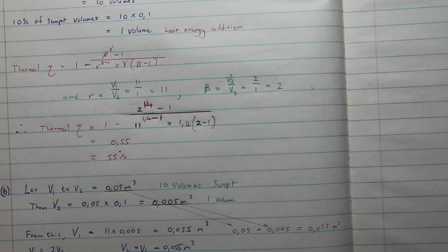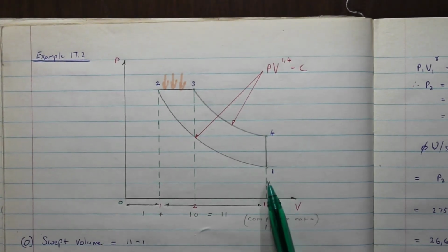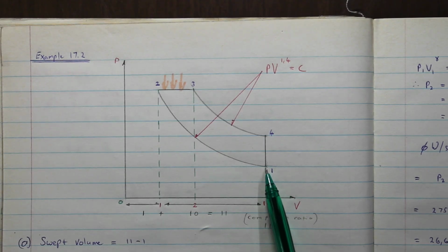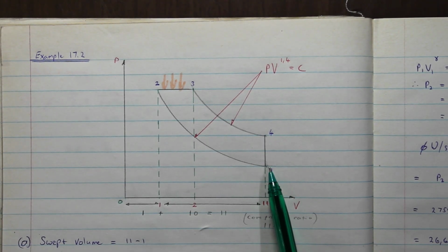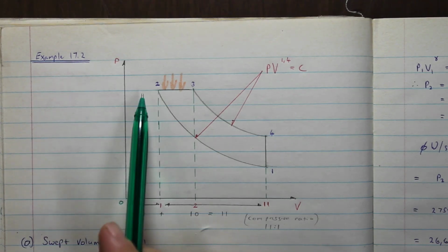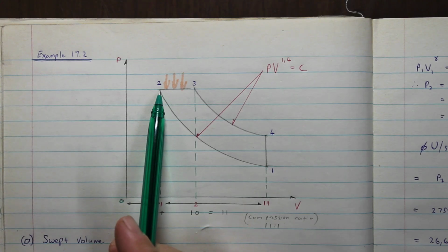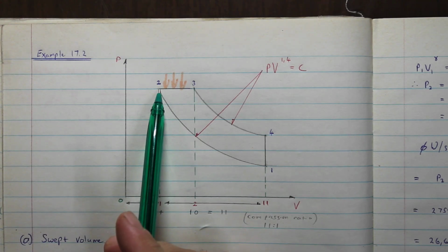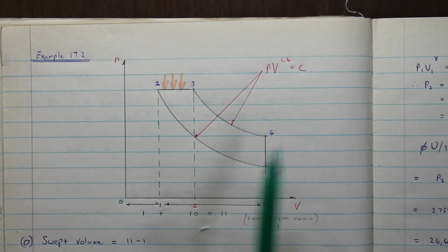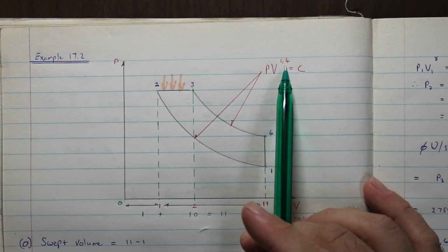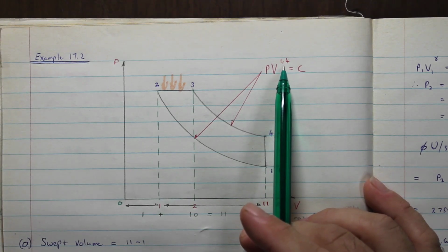Now the pressures. We have the inlet pressure, they told us, at 96 kPa, and they even told us the temperature, which was 18 degrees Celsius. So we know the inlet conditions, the volumes, the pressure and the temperature at 0.1. Now we need to find the pressure at 0.2, and we've already calculated the volume at 0.2. That's helpful. And this process, they told us, is an adiabatic, isentropic, reversible process, because of the 1.4.